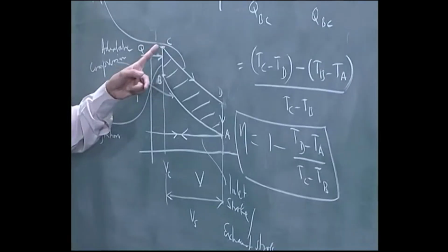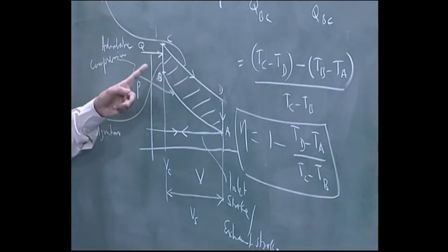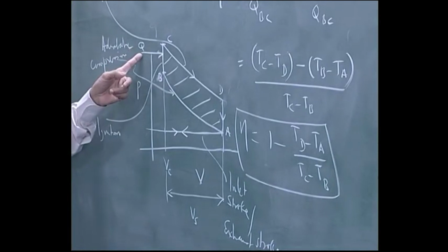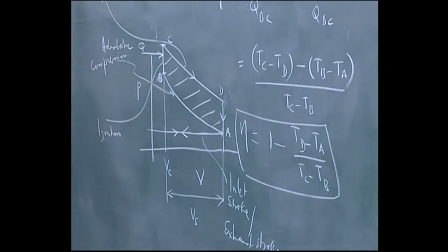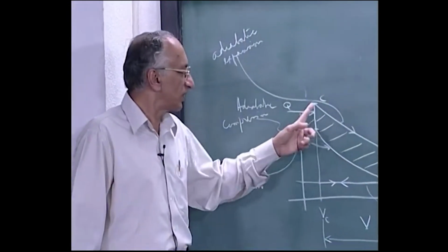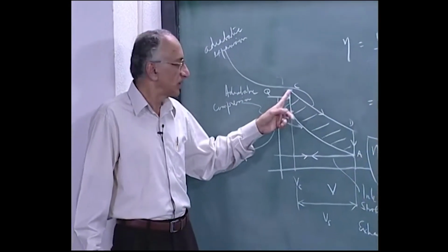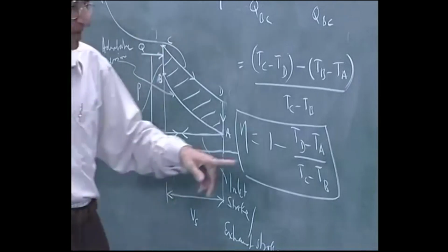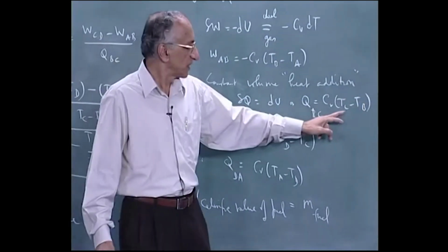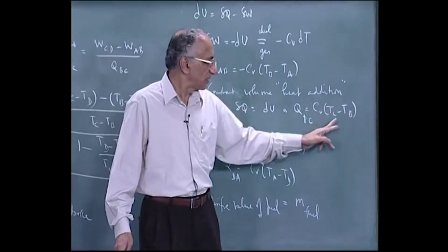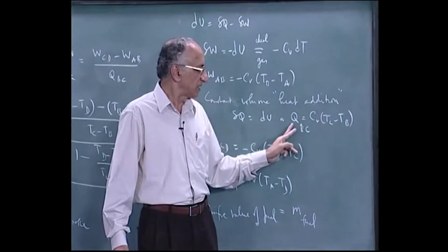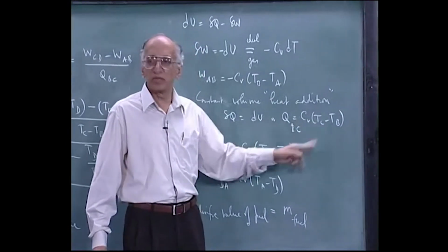Then here again this temperature is known, this temperature is not directly known unless you know the heat addition, that depends on how much fuel you add. So I can give you the fuel consumed, you can multiply it by its calorific value and put in Q here, and so you can get this temperature actually backwards from this equation. That is, I know TB, now I can calculate TC is equal to TB plus QBC by Cv.